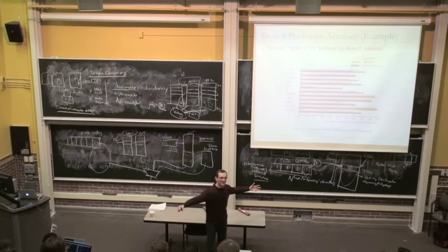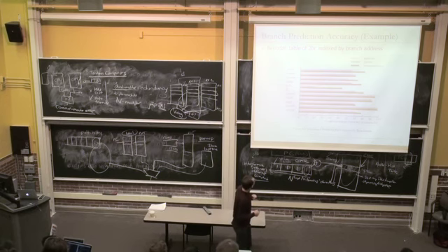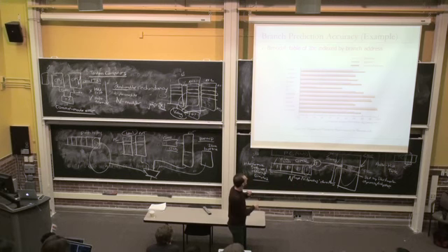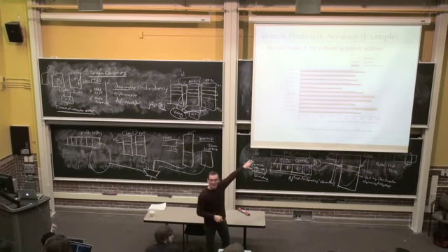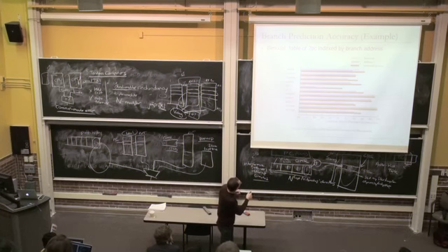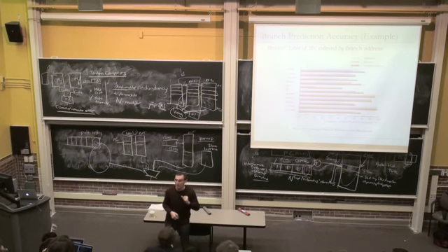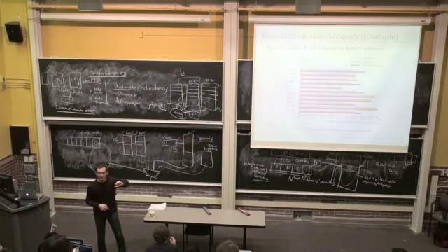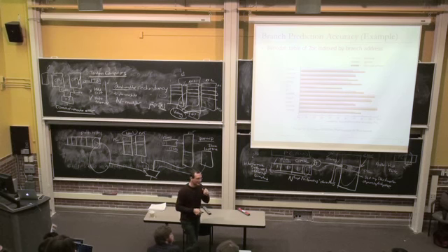Yet still, it's not enough as you increase the pipeline depth, right? Or the width. And you can see that some applications are hard to predict, like GCC. They can benefit from combining the two branch predictors, because neither of the predictors alone is doing well, meaning 85% accuracy. But if you plug in the 85% accuracy number to the slide that I showed you to motivate you earlier, you'll get a horrible execution time, right? So you can actually calculate how much execution time improvement you get going from 85% accuracy to 90% accuracy in that particular machine, and you'll see why people have optimized these predictors over time. That could be a good homework question or an exam question.